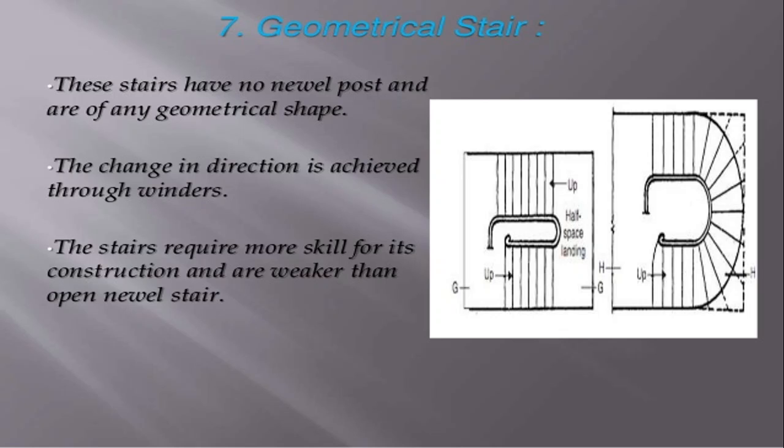Okay, so in these types of stairs, the change of direction is achieved through winders. So they are weaker than open newel post, so more skill is required. This is mainly used to give an architectural inside view, or to provide creative things inside the building.